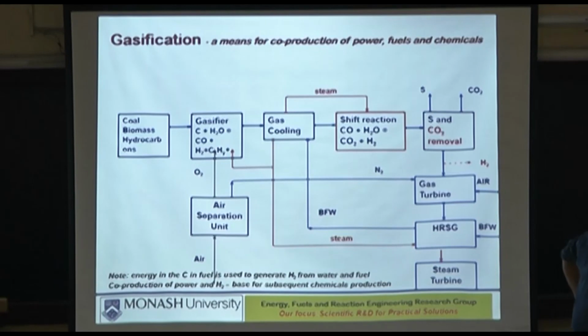First of all, if you are doing the gasification at high temperature, there will be bare minimum tar. When is tar produced? Only when you are pyrolyzing, when the temperature is 500 or so, 400, 500, 300, etc. But in the gasifier, you don't have that temperature anymore.